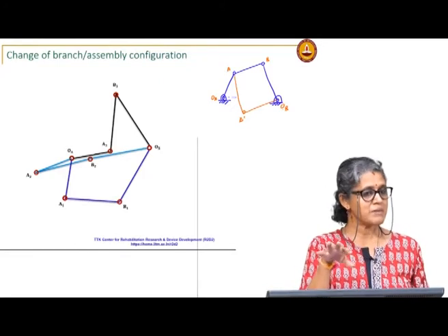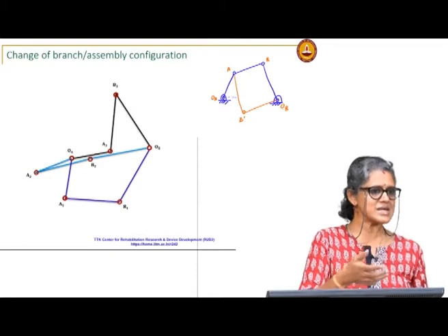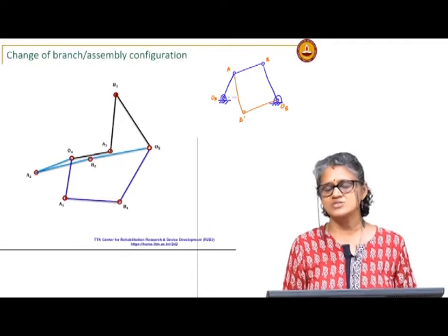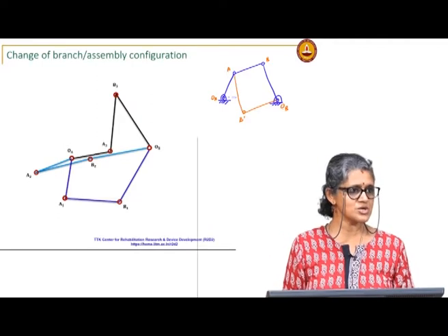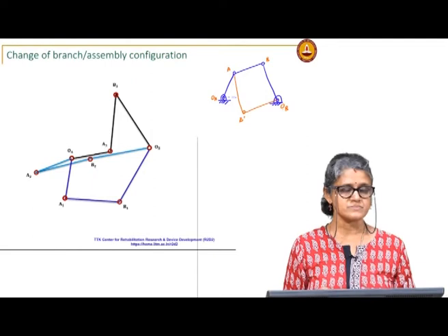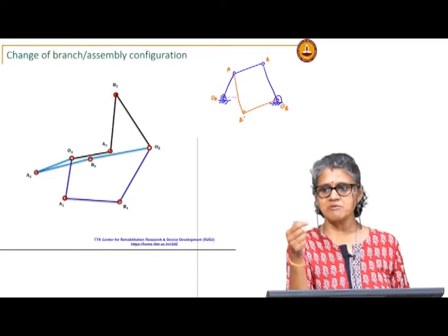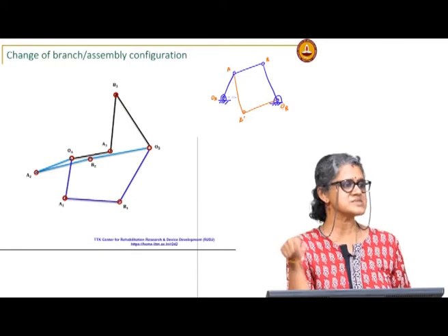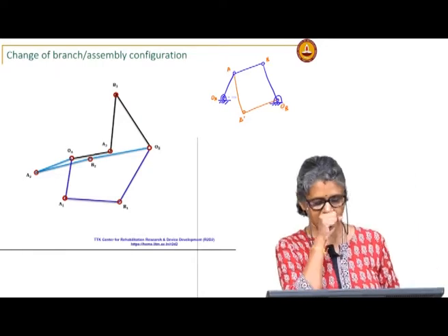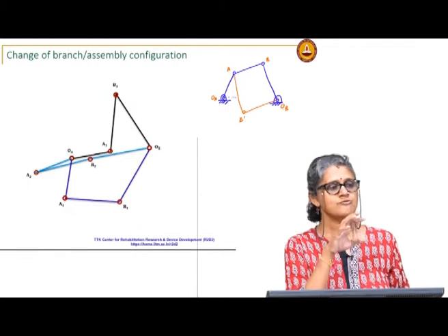The cases where it might happen is if you have a Grashof neutral linkage, not necessarily a parallelogram, but a parallelogram linkage is a Grashof neutral linkage. So, if you have the condition S plus L equal to P plus Q, then when it goes through a change point, it might actually change configurations. But in general, you will not be able to go from one configuration to the other without physically disassembling the linkage.